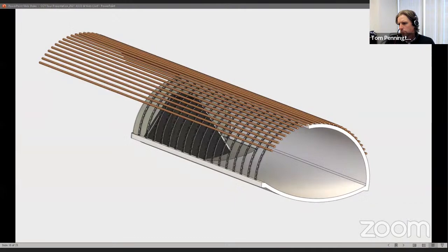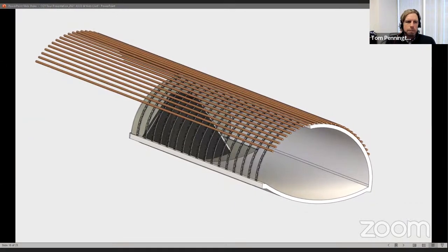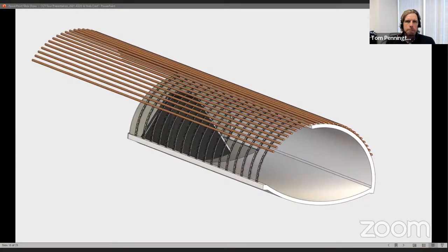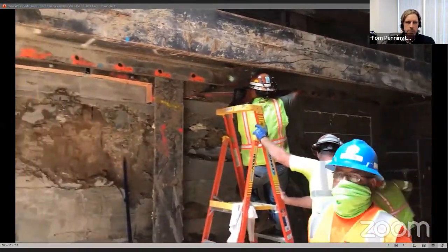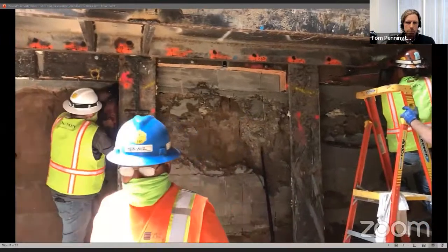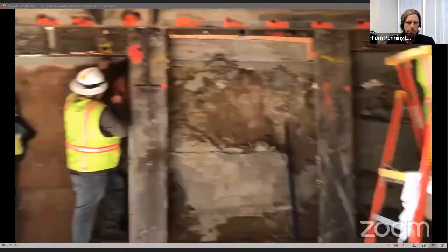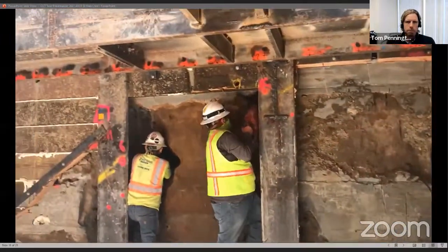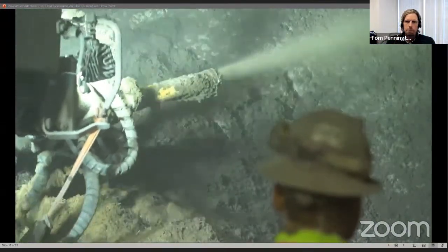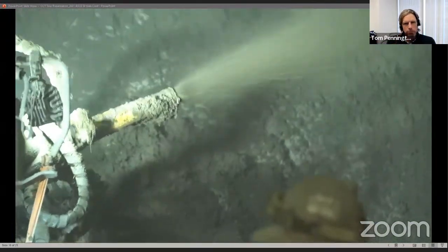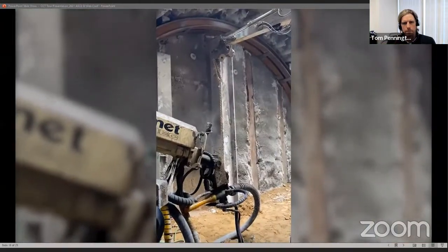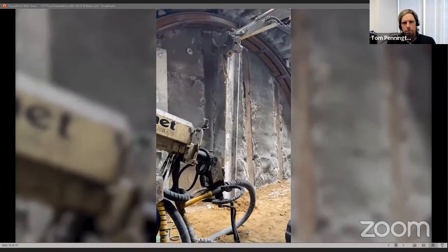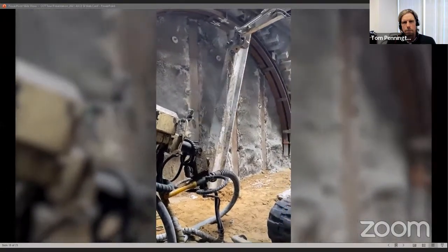The canopy pipes are commonly referred to as tunnel pre-support, since the pipes are put in place prior to excavating underneath them. Upon completion of the first canopy pipe array, the lagging boards between soldier piles in the window of the tunnel were removed, and temporary support consisting of a layer of shotcrete was added. After this support was in place, the soldier piles were cut out and a collar beam was installed around the tunnel opening, which is the final step before excavation of the tunnel could begin.